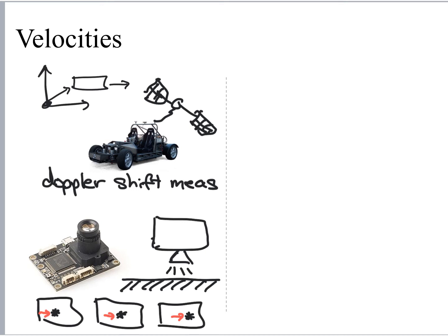On the angular side, again, we run into the same problem of being able to make a direct measurement as something rotates around. Obviously, because two objects, if they share an axis, if we can put the stationary part of the sensor and the moving part of the sensor on the same axis, they'll rotate around and around. And so we could use this relative rotation, but again, we'd be differentiating a position measurement if we used an encoder or something like that.